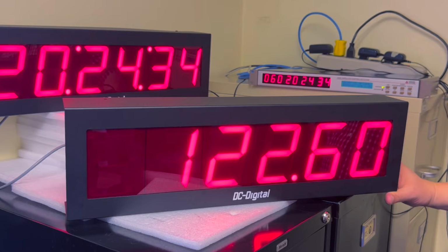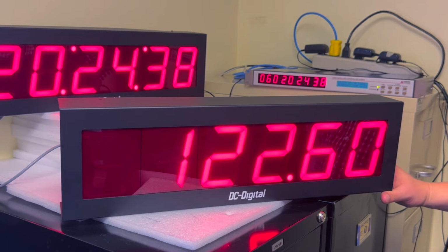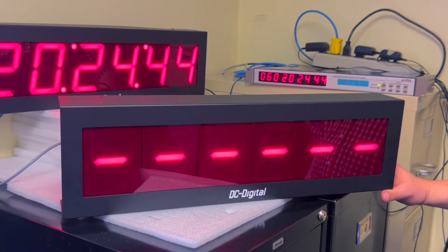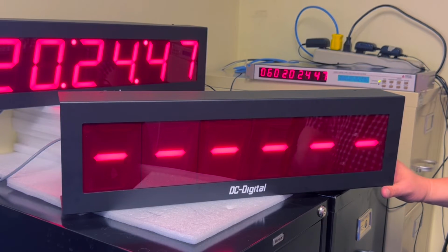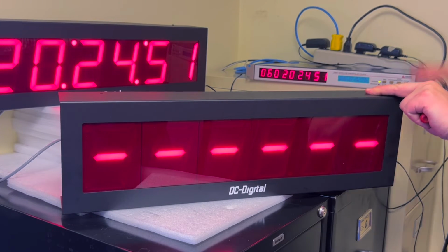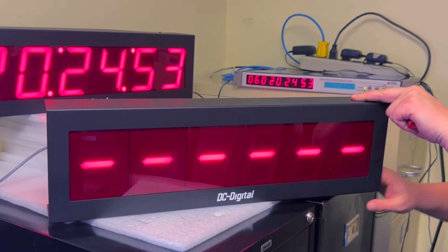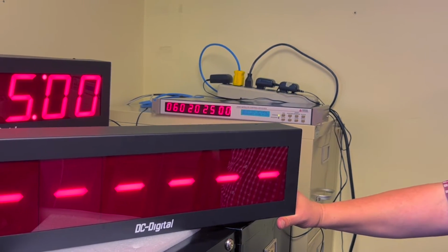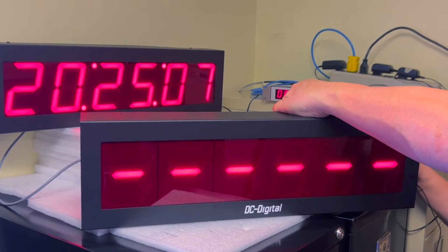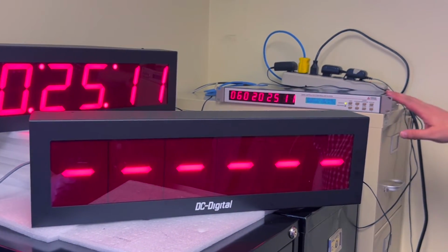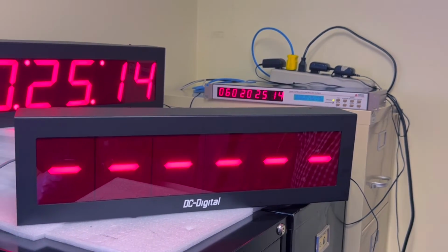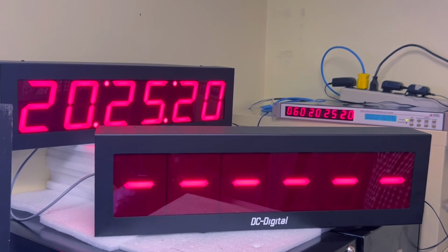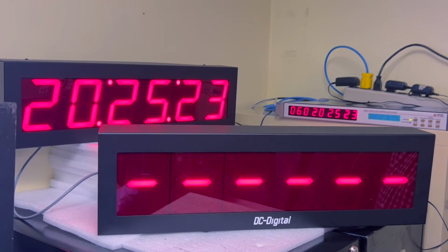So if we are looking for one mode, say we're in mode 6, but that data is not available or doesn't come through for any reason, we will show blanks across this display, showing that that data is not available. First thing that I would check is your box here and make sure that it's set to the Vorne standard output, in order to have these different addresses come out of your serial port. There are other outputs that Arbiter makes, not just the Vorne output, but this particular product is addressing that string. We can custom manufacture for any of those strings that they have available in their clocks.